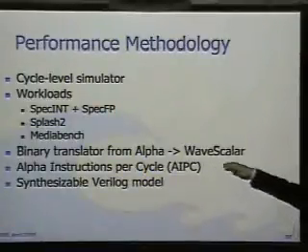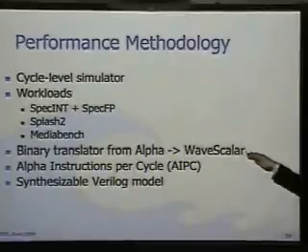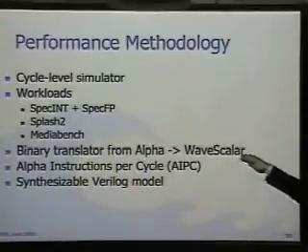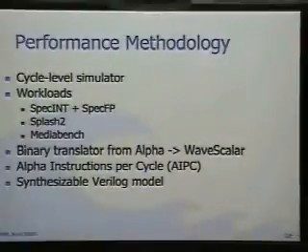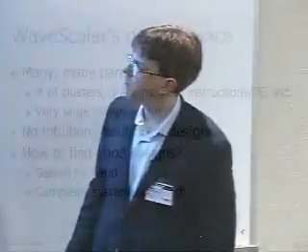So what this means is that we ignore the WaveScalar specific instructions that are added during this binary translation process, so that our AIPC numbers are directly comparable to the IPC numbers that you would see in more conventional processors. We also have a synthesizable Verilog model that's going to provide area and delay measurements that I'll talk about briefly.